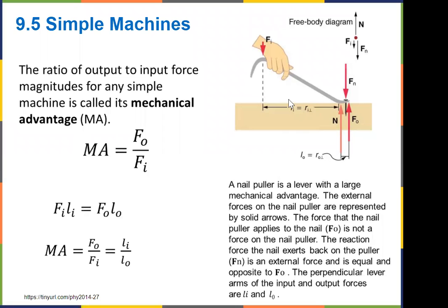That's because we are applying torque over here. This lever arm is further away from the pivot point, which will be the x rotation. Then this small lever arm here is for the nail, where the force is applied directly to the nail. So by applying a small force over here, you can pick the nail out.